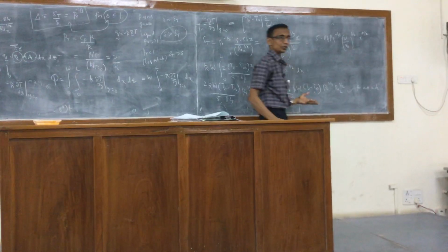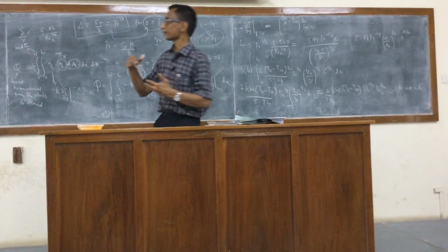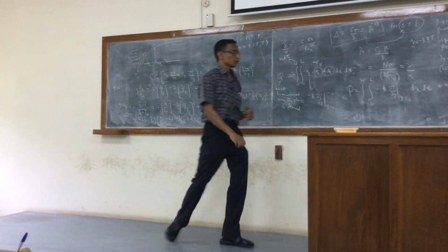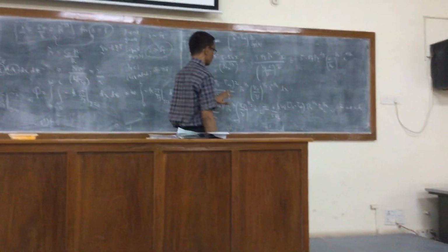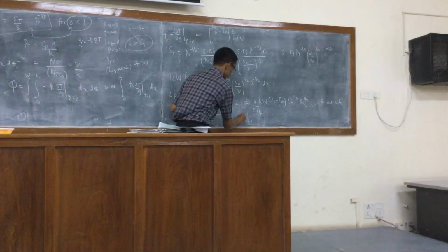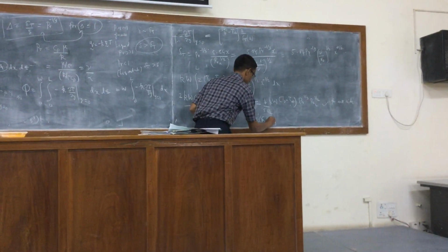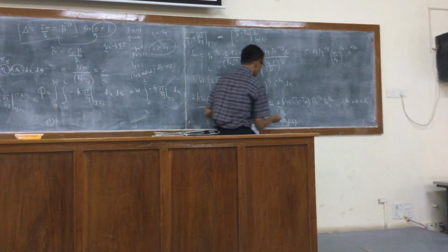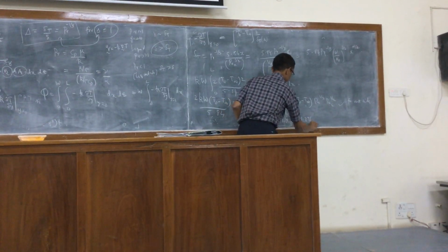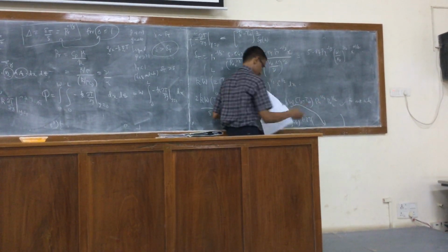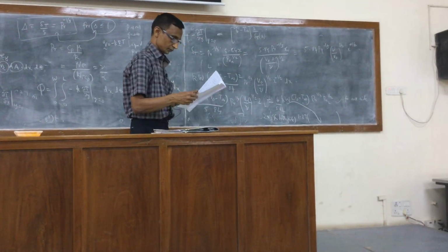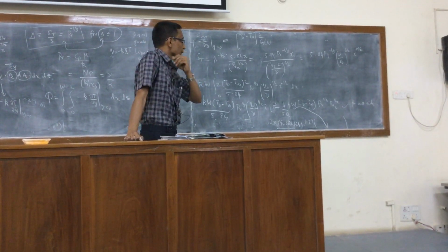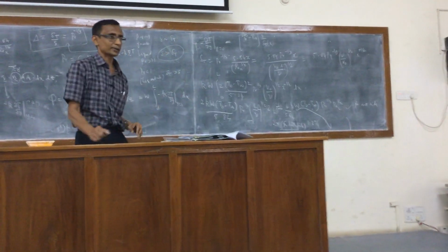The answer in first to x is twice this. Because as I said, we have fluids flowing all around the plate, I have made the calculation for only one side. So for one side of the plate, this is correct. So the final answer would be 2 times this, so 2 times for both sides. And the coefficient alone, I write the 8 by 5.8, so that's 1.37 times all of this. So it's Prandtl number to the power 1/3, Reynolds number to the power half. Those are somewhat characteristic exponents.